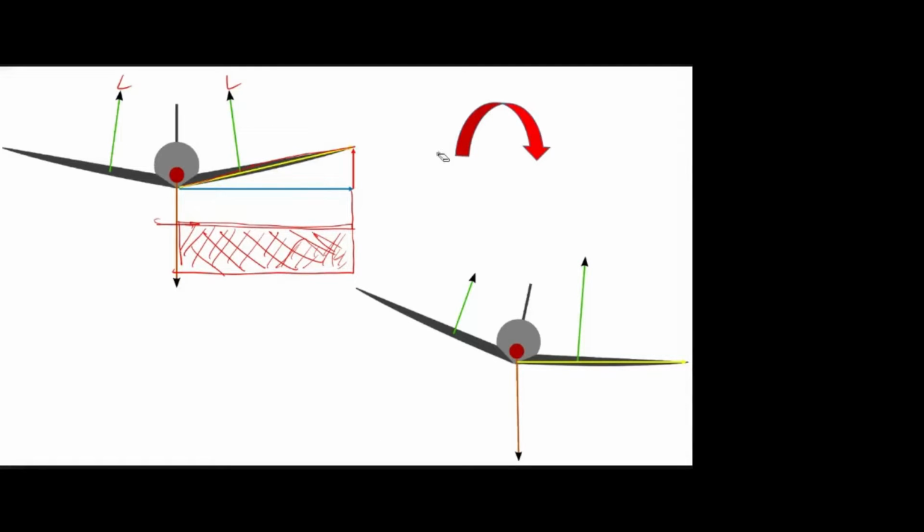Now assume this aircraft is side slipping. Due to the side slip, this wing is coming to the horizontal direction. Now if you see the reference area, this time you have to take that yellow color line. Compared to this blue color line, this yellow color line is longer, as this is a right angle triangle. So this line length is more, then this area is more, then this wing produces more lift compared to the other.